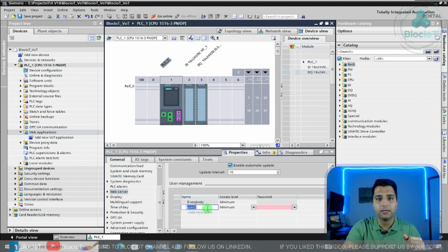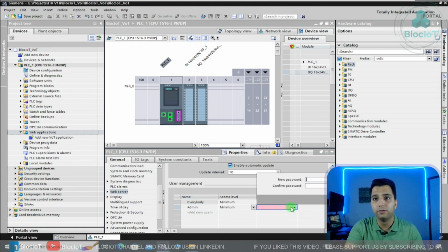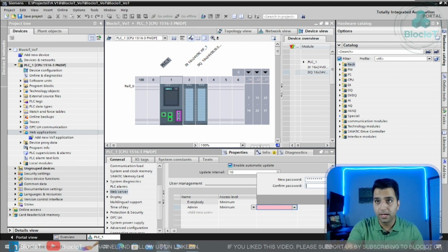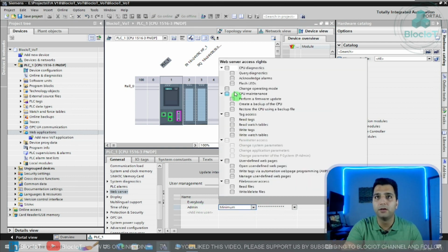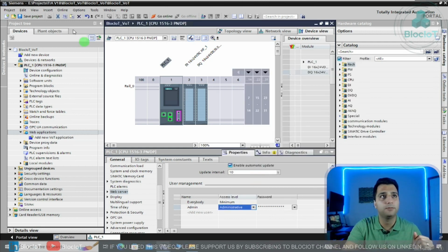And you can add a user. You have to do that because you need to log into your web dashboard or HMI. I just pick a simple password. And you need to define what kind of access this user has, because this is an admin, I just give access to everything. But for just using View of Things, the minimum requirement is the tag access, because you want to interact with the PLC tags. Okay, and that's about the web server.